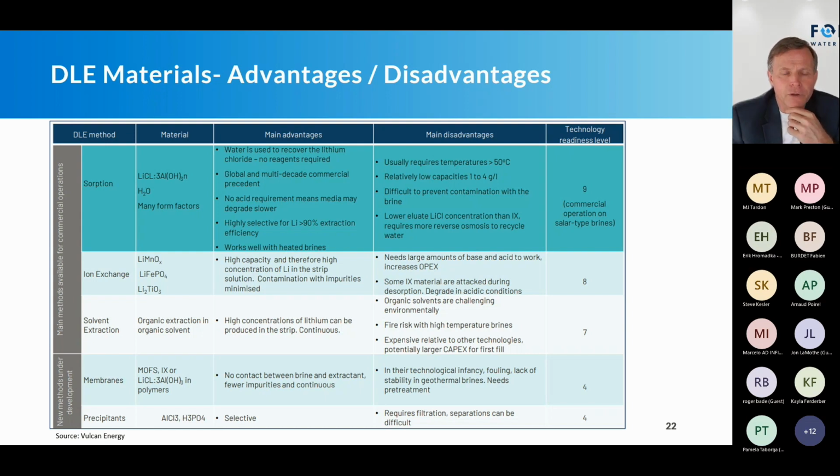So there is the other component: because I'm using water, I'm not going to have waste reagents, which I'd have to get rid of later on. Different materials, as I said, could be aluminum-based, magnesium-based, titanium-based for absorption materials. The efficiency depends on the supplier. You're looking anywhere from, I'm going to say, 80% all the way up. Some have even posted 100% efficiency. Again, posted. I haven't seen the data on that, but that's the range you're seeing.